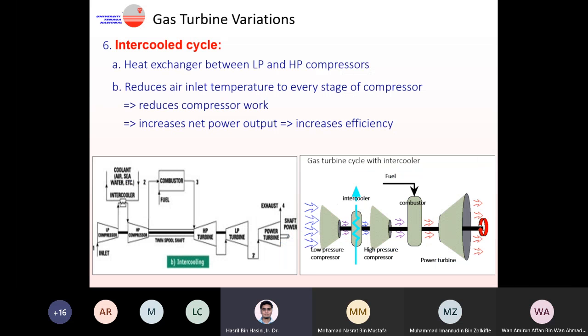Okay, then we have intercooling, the intercool cycle. I think most of the power plants are adopting this. Before we proceed to the intercool cycle, let's have a look at the basic operations of our compressor. Actually, in our compressor, we can also break it down into a low pressure compressor and a high pressure (HP) compressor.